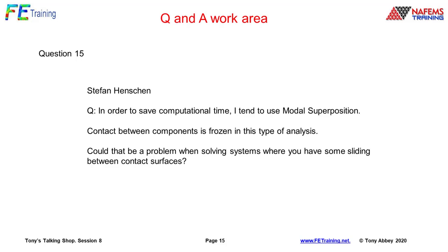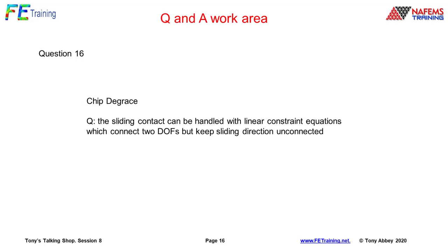We put the slot in there, we're constraining that component to move within that slot. We're usually driving the frequency up. So if we have some estimate of that, we can put in local springs to drive those frequencies up. That would be part of the process I would go through if I wanted to avoid more complex nonlinear transient analysis.